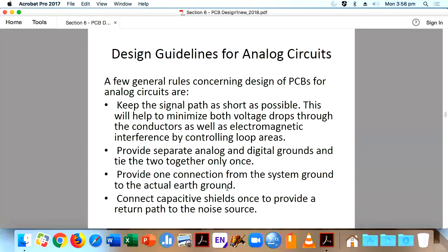Your system is within the aluminum, and that is a chassis, we call it the chassis. That one has a ground, and inside, your signal PCB has a ground. And this chassis you can't make floating. So what you do is use a grounding isolation technique. You might be using an optocoupler or some kind of isolation. We will study isolation techniques. That will connect your signal ground to chassis ground. It is not physically connecting a wire, it is isolation, but it's connected. So that is an earth ground.